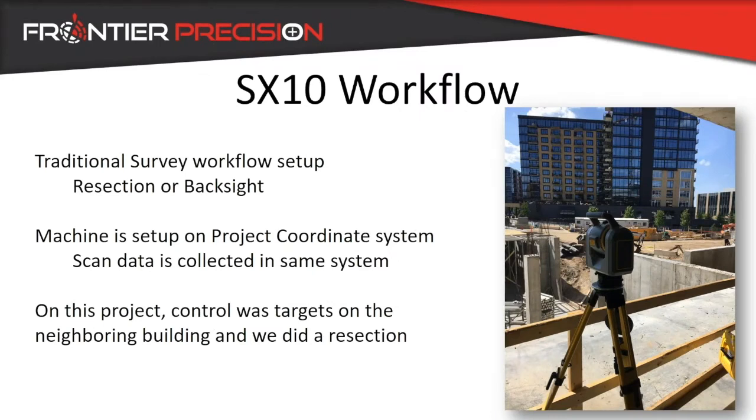All right, so the SX10 workflow that I used for this example, or that you can use, period, is one of the benefits. You can do a traditional survey workflow. With a traditional 3D laser scanner, actually having the project control on site is a little bit difficult to do. With the SX10, you can do your resection, you can do your backsite, whatever you want, and you're in your project coordinates automatically.